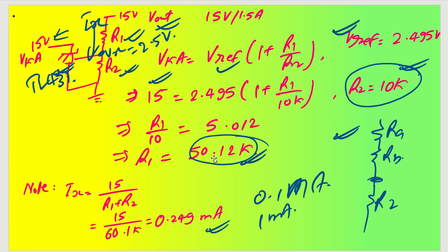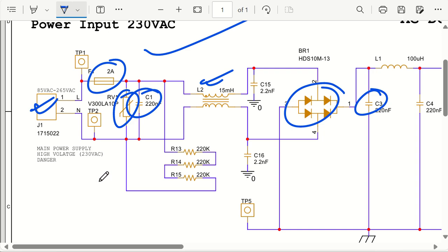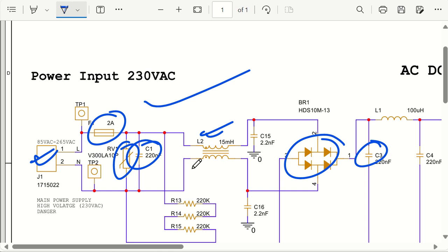All right, now let us do the circuit. As you can see in the circuit, I have selected a 2 ampere fuse. For the selection criteria you already know, in the component selection process I told you that the rating of this fuse must be, let us say, 300 volt AC, because it will be working at 230 volt or 265 volt AC, so I don't want it to fail below 300 volt. So 300 volt AC, 2 ampere rating for AC DC application.